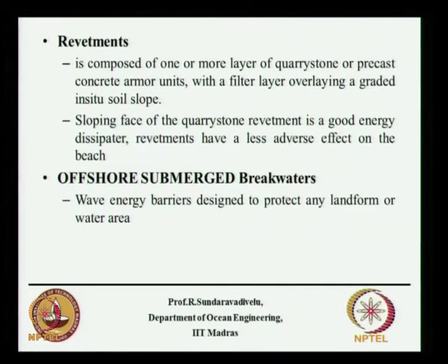Revetments: on the beach itself we put some filter layer and then put some armor units, this is called a revetment. So this revetment is also an energy dissipator, and it has less adverse effect on the beach. We have one more concept called the offshore submerged breakwater. These offshore submerged breakwaters are built in the sea and act as wave energy barriers and protect the landform or water area. So let us see by sketch all the different types.